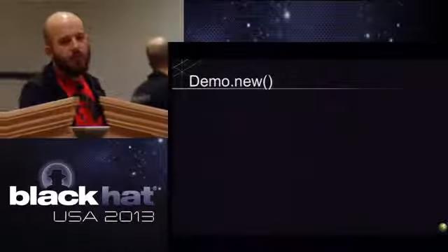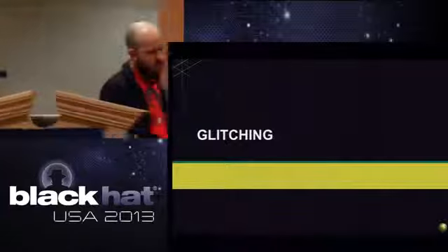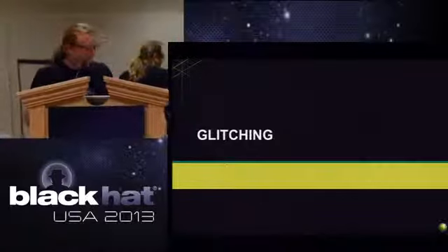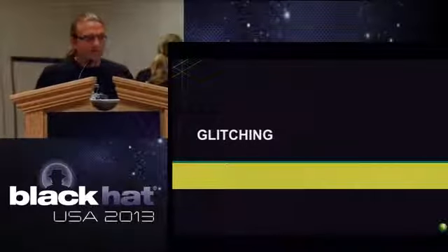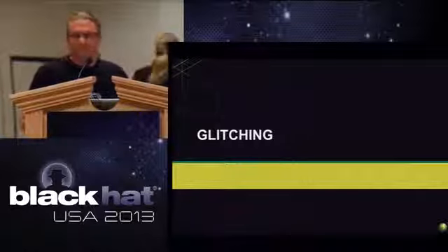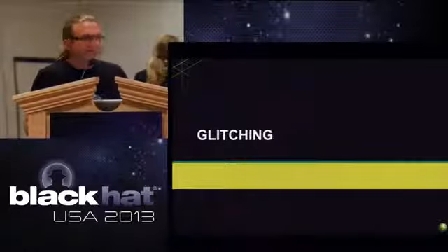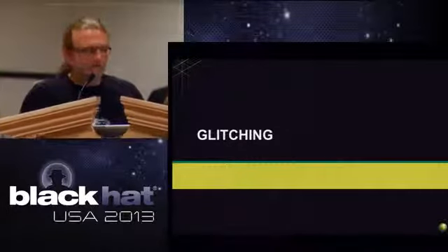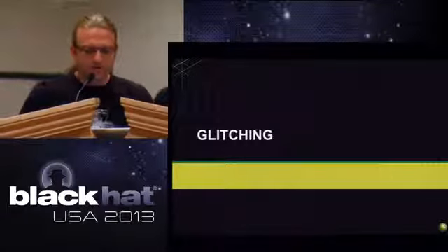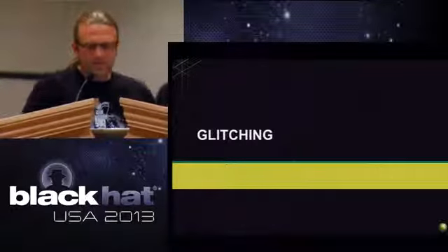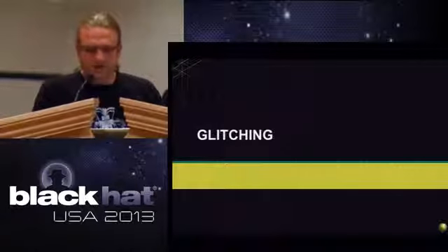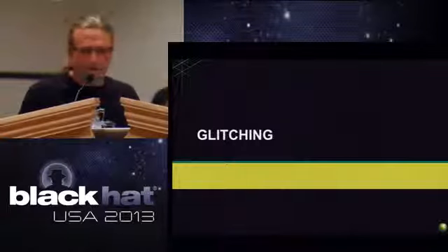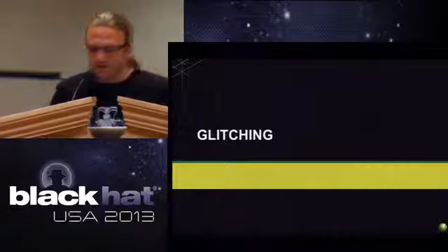I think we've got a couple minutes that we'll cover glitching real quick. If you remember way back, we talked about there being some bits that can be set that don't let ICE be enabled anymore, so you can't actually do any live debugging on the board, unless you magically hit it within that first 30 to 60 cycles. Once you do, you can get away from that. But we wanted to do something a little sexier, and it was one of the reasons we're not releasing the GoodFet code, because we went tangential down this path and the GoodFet just couldn't quite keep up with where we wanted to go. We will get there and release it hopefully at some point.